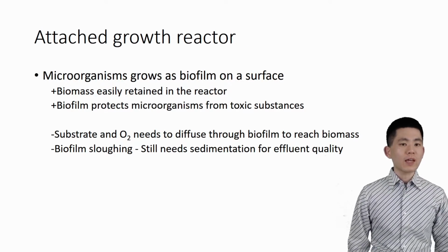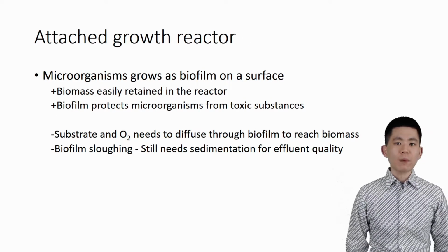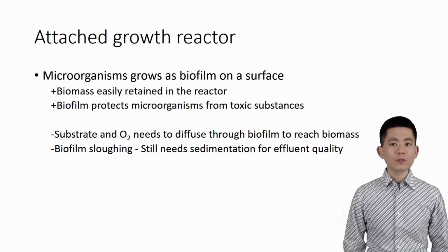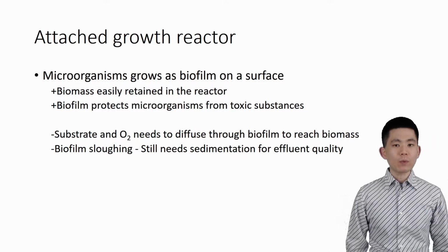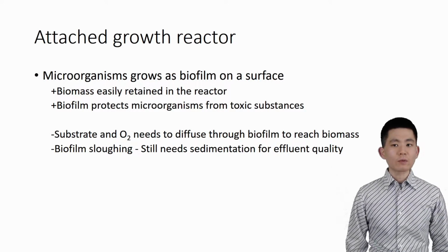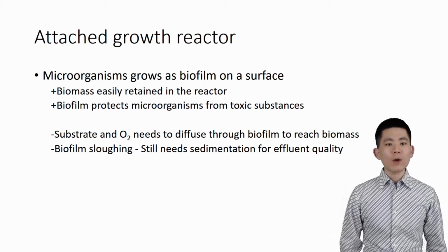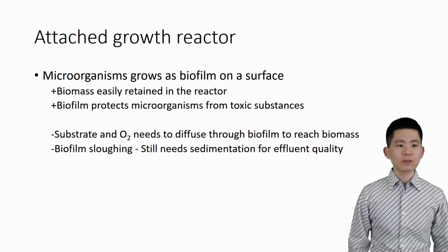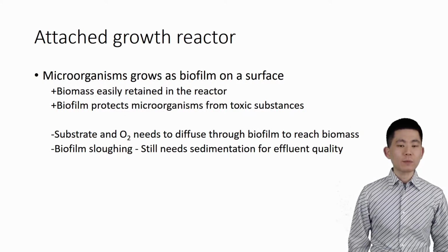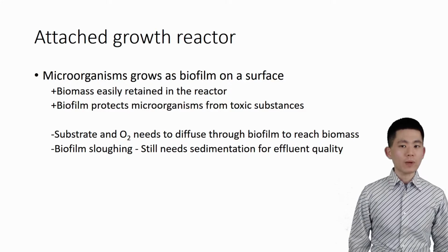As for the attached growth reactors, because the biomass aggregates in biofilms and attaches on surfaces, they're easily separated from the bulk solution and retained in the reactor at high concentrations. Also, the biofilm acts as a barrier between the biomass and toxic substances, protecting the biomass from shock loadings of inhibitory compounds.